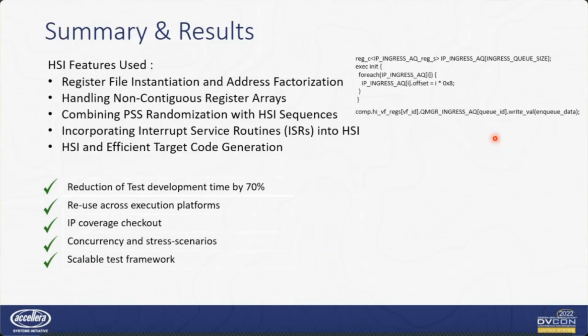In the long term, the big benefit we see with HSI is that you can use the best target platform for the best task. What I mean by this is you can develop your HSI code in, let's say, an IP level UVM environment where the runtime would be small, so that by the time you reach emulation, you can run much longer, complicated test cases, and you don't have to waste cycles developing test code.